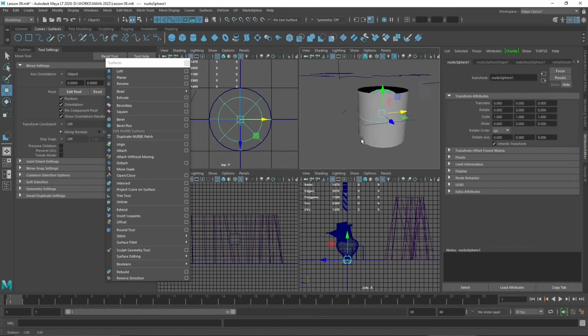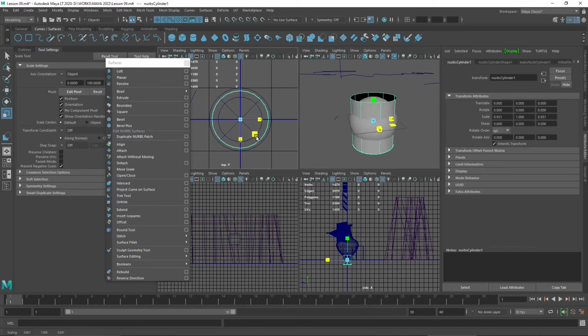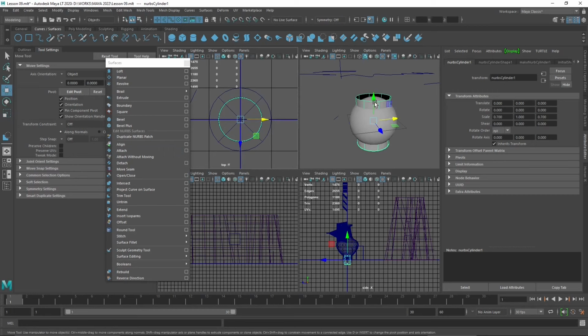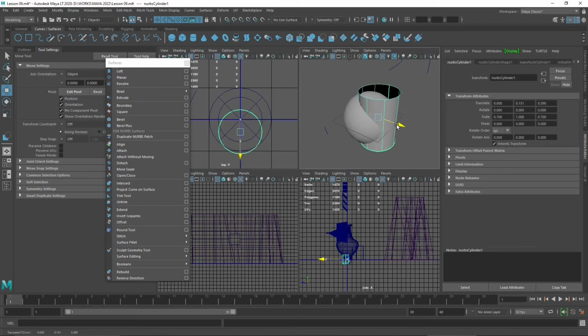In this case, I'm not using a curve to create an object, or an object to project a curve, or other things that we already saw, but I'm using two objects. The cylinder is not actually a solid, but an open polysurface. So I'm using one closed polysurface and one open polysurface to create a curve, which will be there where the two objects intersect with each other.